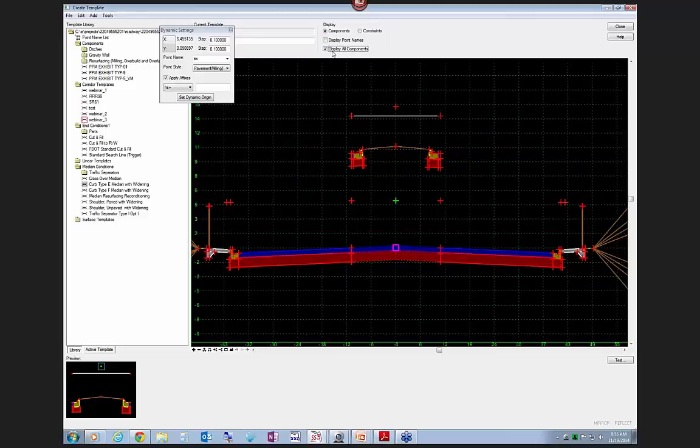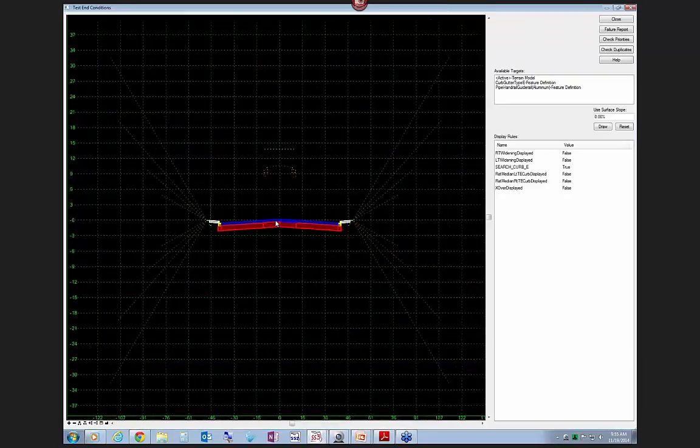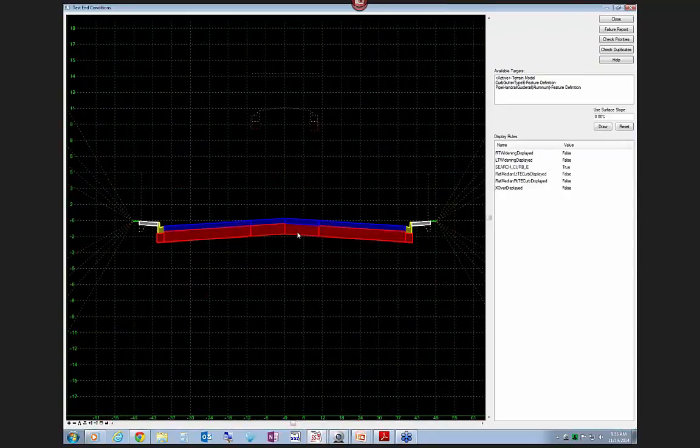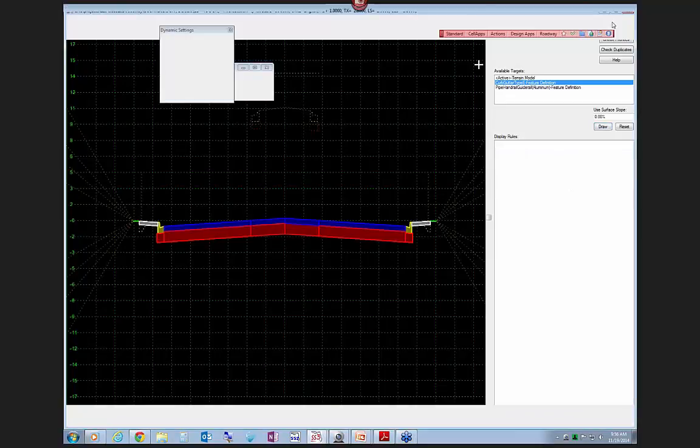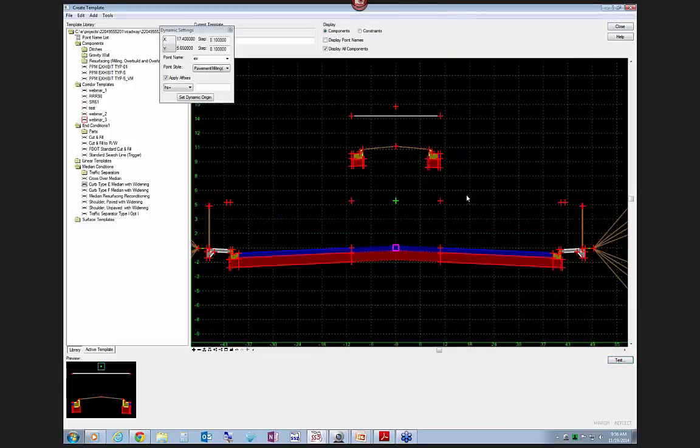And now notice that the crossover median now is dashed out. And if you test it, you'll see that because there's no curb median, the crossover is solved. As soon as I add a target and solve the target for the curb median, then the crossover turns off. It's that simple. At least it's that simple to me.